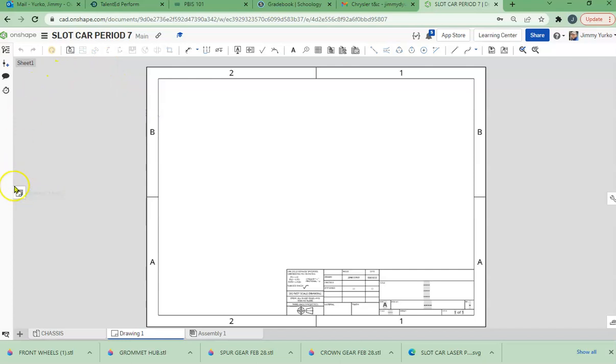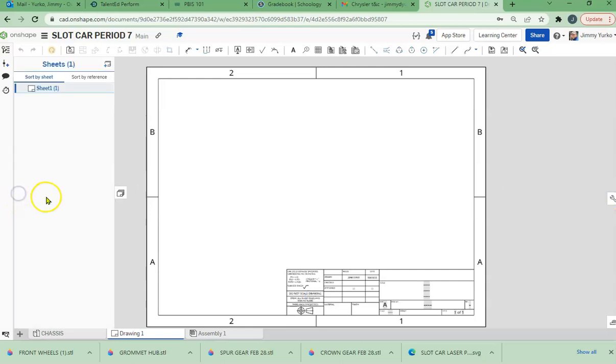We're going to open up our side pane. We have side panes on the left and the right in our drawing space. So you can see that we have a border, title block, and of course the file name and all of our tools. And then you can see just like in our Part Studio, we have a sidebar. We have a sidebar in the Drawing Studio as well. So we're going to rename that. We're going to just call that cover sheet.